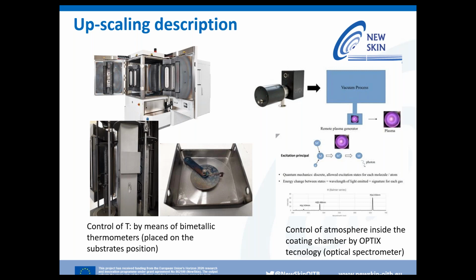It's an optical spectrometer that gives you information about the species present in the vacuum, and can also give information to another unit, a speed flow controller from Gencoa, that controls the flow of the gases in reactive magnetron sputtering processes, in order to have closed loop control for these processes that is sometimes very complicated to achieve without this system.